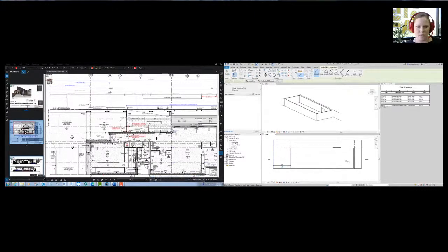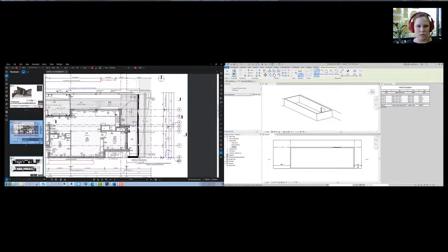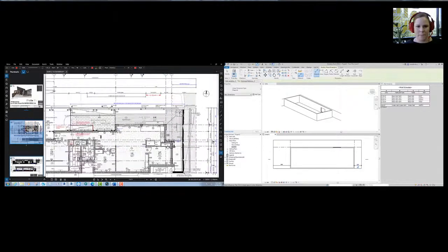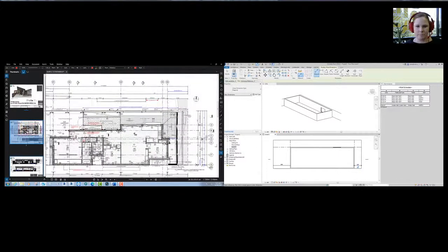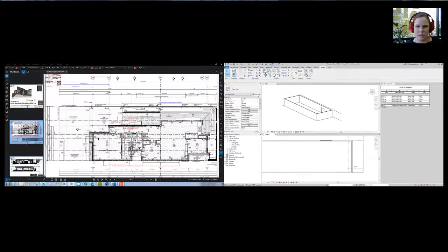I am just checking the offsets. So what I want to do is, although the council offsets might give you a certain value, you might think in terms of your sustainability knowledge that you want to increase those setbacks or things like that. So I'm just doing a measurement on there and changing it, 3.5 meters, and I'm just going to align the outer face of that wall.